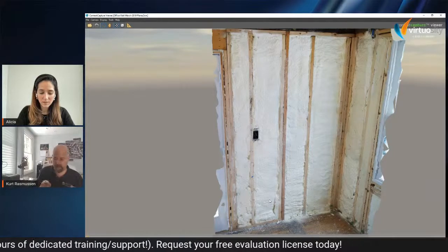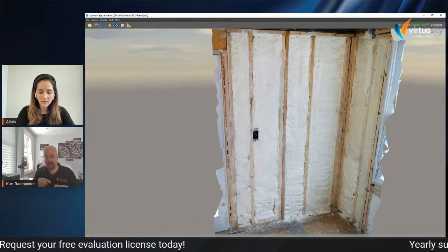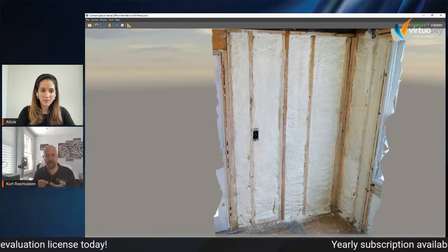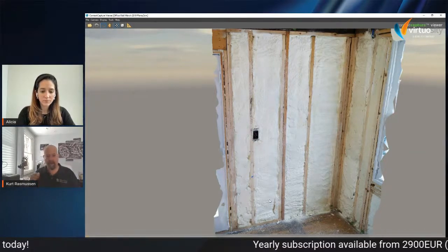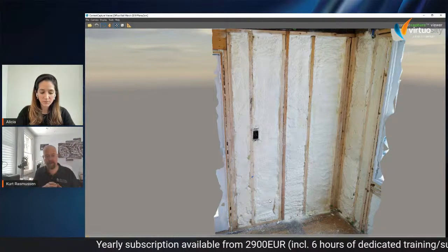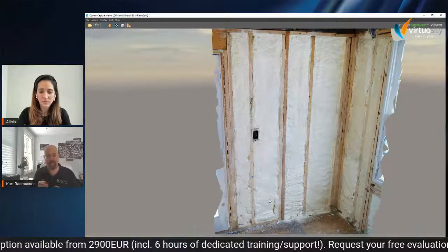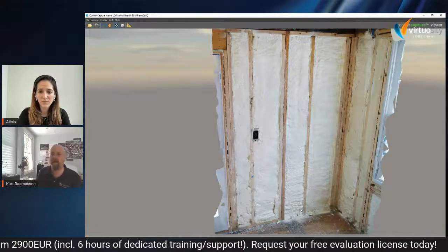I had this metal poker. I actually have it somewhere here. This metal poker that I put electrical tape 3 inches up on it. So this way I could punch it through the foam till it hit the board behind it, and then I could see if I hit that mark, which means I have 3 inches of foam. But I'll get into the R values then.